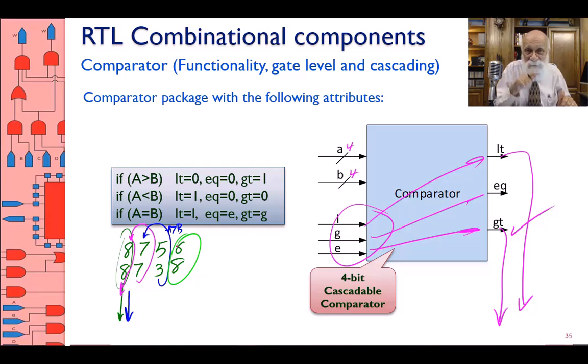Nobody listens to it because listening stops when the digits to the left are no longer equal. So this one, if you look at its own output, it's saying B is greater than A. But then the blue slice is saying, look, I've already made a decision, and those guys to my left have already taken that decision and announced it through the output.